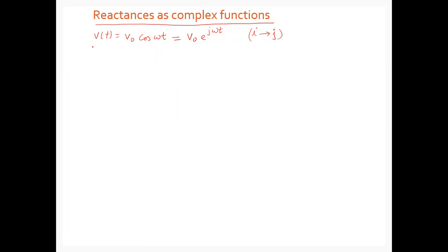So now let's do the capacitor current. Now what happens in the capacitor? Number one, let's do the capacitor. In the case of the capacitor, what do you get? I is dq over dt. And in the capacitor, what is your Q? Q equals CV. C equals Q over V, right? So remember, this gives me this. So then C is constant, you can pull it out. So dV over dt.